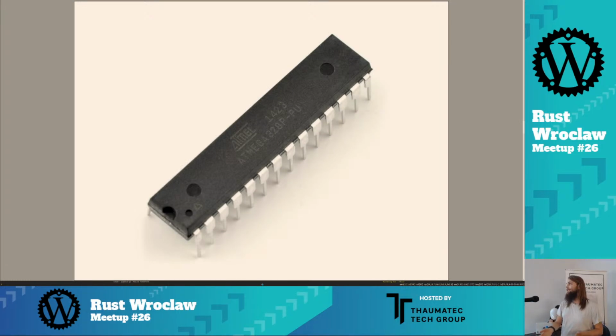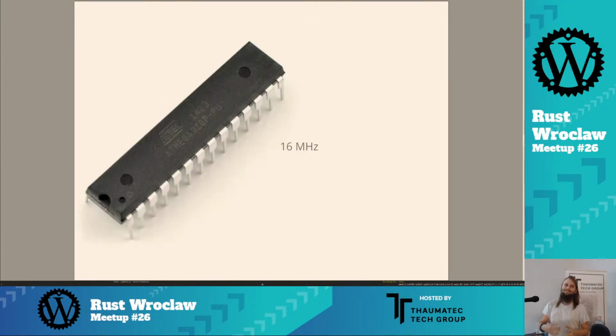So I said they are kinda like mini computers, so maybe let's compare them to a computer. This little boy can be clocked at various frequencies. Usually you will get around 16 megahertz. So this in practice means it can do 1 addition per clock, so about 16 million additions per second.